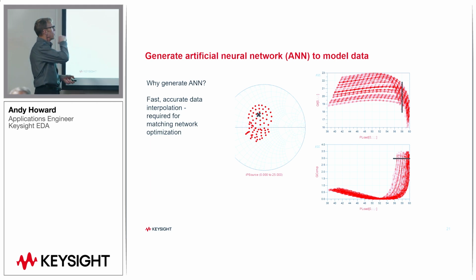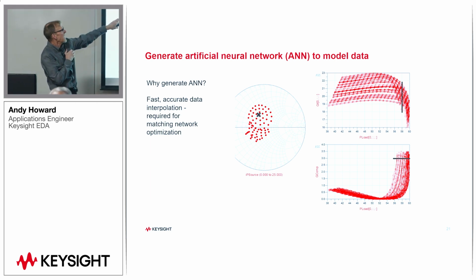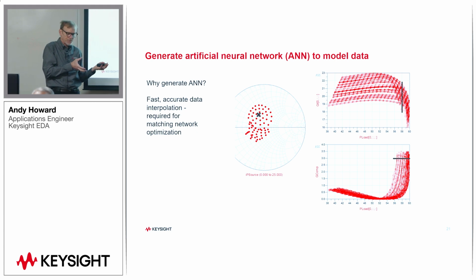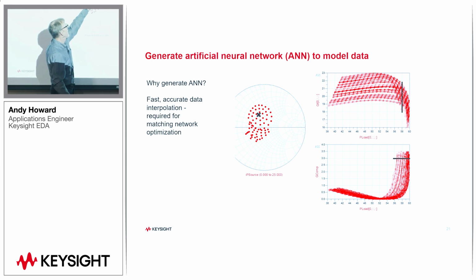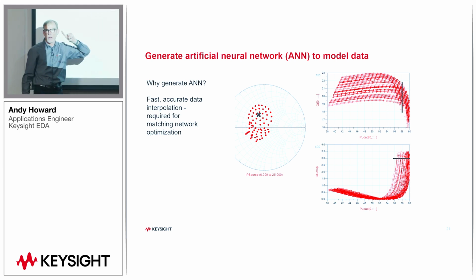And when you're optimizing, we want to take this data and optimize an impedance matching network based on this data. When you do an optimization, you have a candidate matching network, and the optimizer picks parameter values in the matching network, runs a simulation, and you get load reflection coefficients that are generated. So you get an impedance value. So this X would be, for example, the result of one optimization trial.